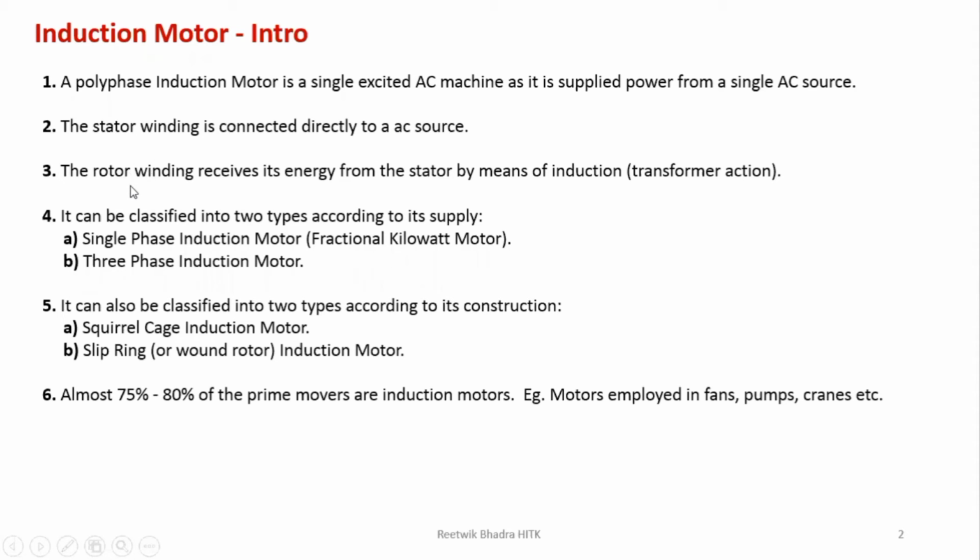And on the rotor side are conductors which are placed in slots. So that rotor receives the energy from the stator by means of induction. So whatever you have learned in transformer, whatever you have learned in three-phase, all those things come over here. So supply is three-phase, working principle is based on transformer action. How the transformer operates, you have a supply to the primary, then a flux is produced in the primary, which gets linked with the secondary. Then there in the secondary EMF is produced.